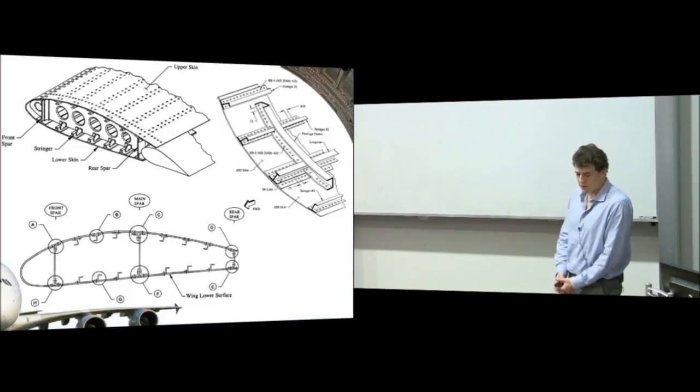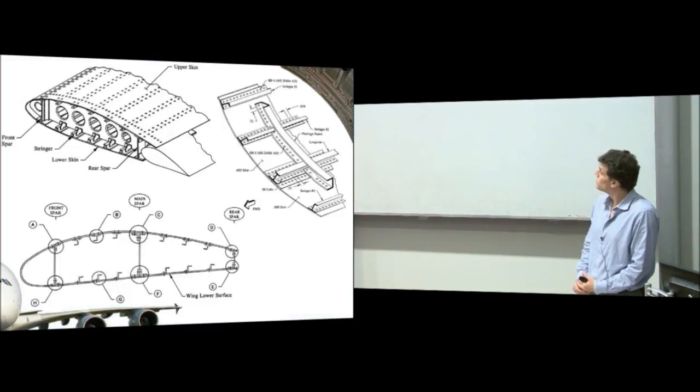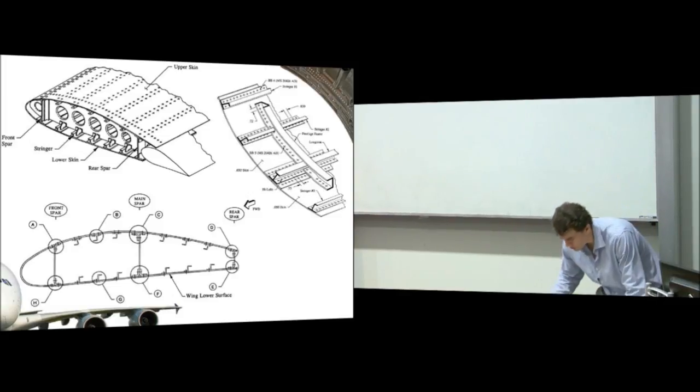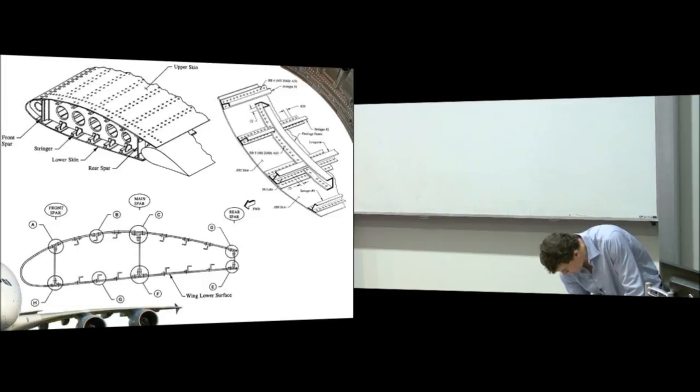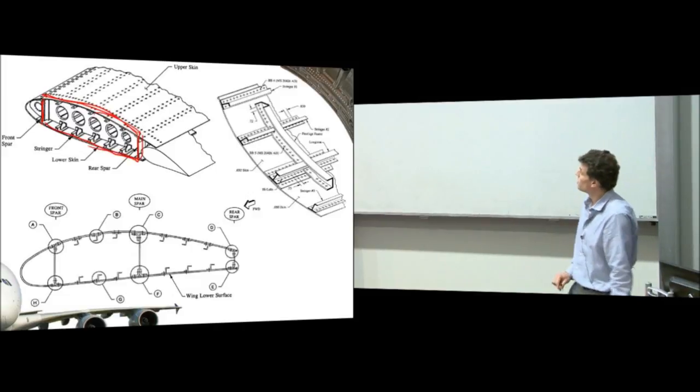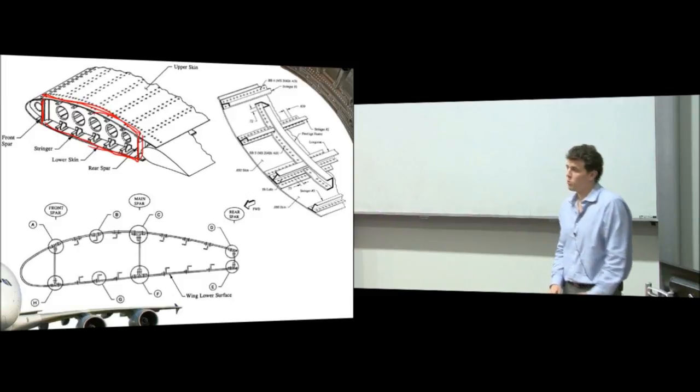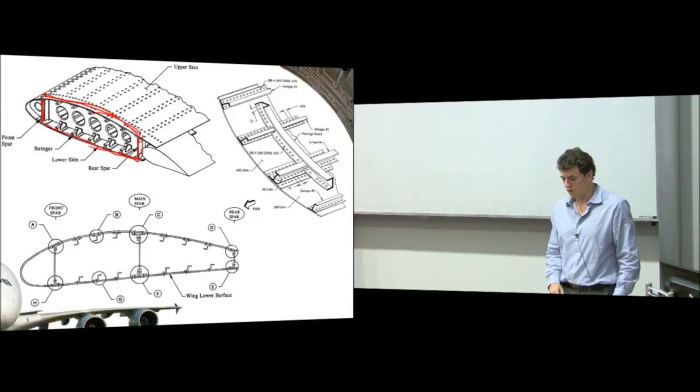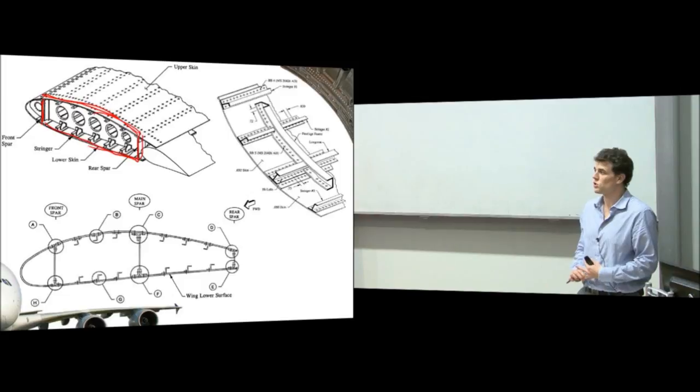And again, this is a bit more of a closer view at pieces of structure. So up in the top left here, we have a wing box or a wing cross section, and the wing box is defined, remember, by the front spar, the skin, the rear spar, and the skin. This is what we call the wing box. Okay, it's a box shape. And the reason we have boxes as opposed to open bits of structure is that they're, as we learnt last week, much better at resisting torsion than an open section. So we have closed cells generally in our wings.